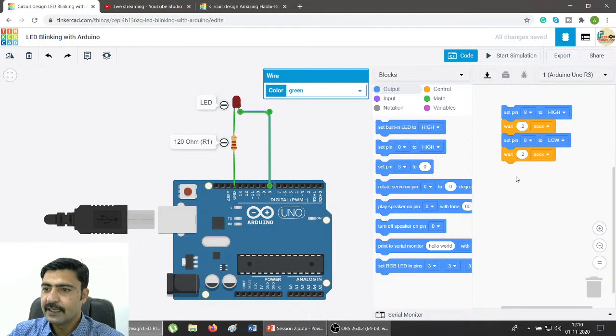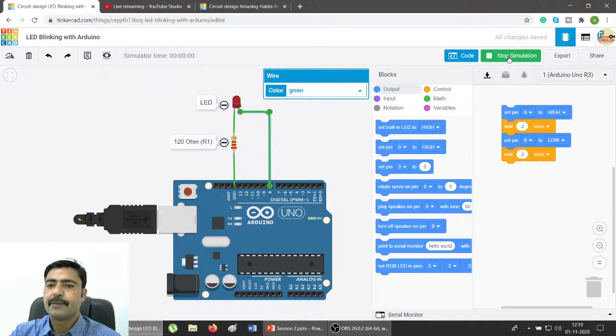So I have connected it. Now let's check the program. So again the LED is blinking at a rate of 0.2 or 200 millisecond, but in this case we have connected our LED to pin number 8 of the Arduino board. Have you got it? Do you have any confusion? Write in the comment section. Anything you want to ask at this particular moment related to this interfacing project?